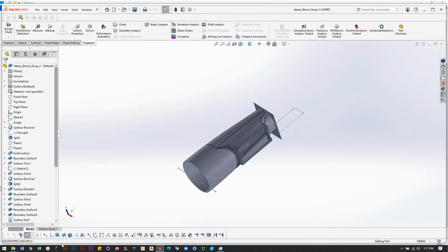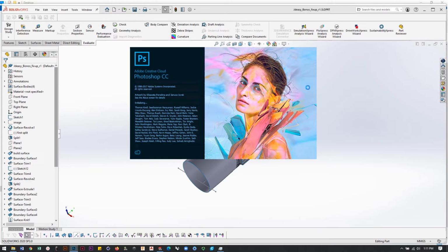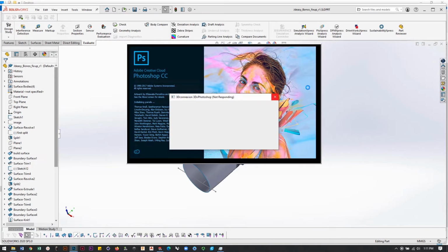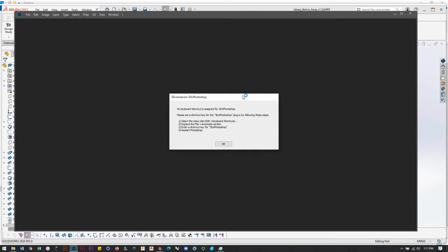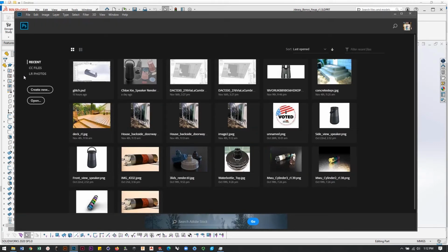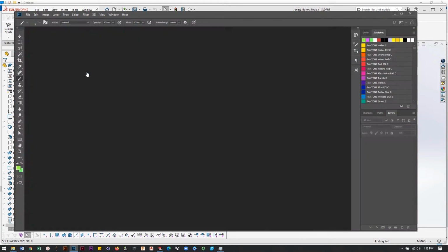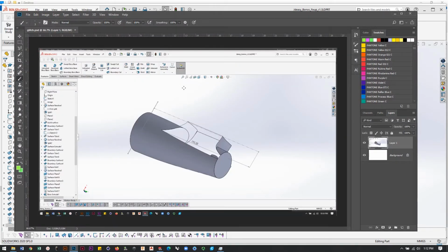In some of my rebuilds, I had absolutely terrible problems coming up. I really can't explain what was happening, but I seemed to be having computer glitches. I had portions of the model that were disappearing or showing up as transparent when they shouldn't be. I had strange artifacts jumping up throughout the build, and I really just couldn't seem to get a handle on the thing at all. And when you get into that scenario, I am so sorry to say, but as I mentioned in class, starting from scratch with a brand new file is a good plan.